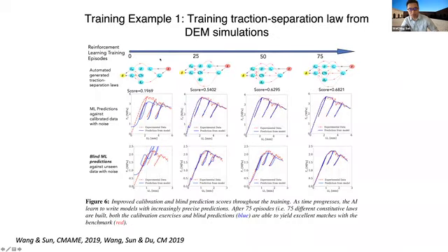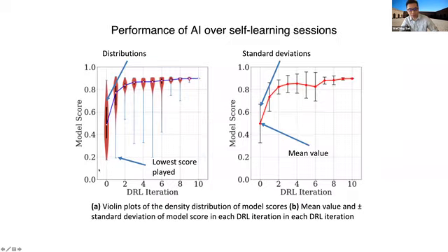So we can see here we have 75 episodes, which means 75 different constitutive laws, not written by us but automatically generated by the AI. Each time it generates a better response. At the end, after just 75, the traction separation law predicts pretty good results. Initially the model is exploring different techniques to write a model, and eventually we cool down the temperature to yield a converged response.